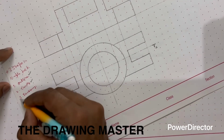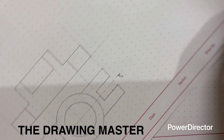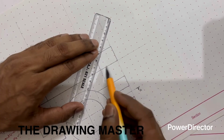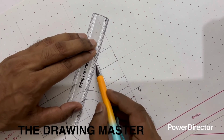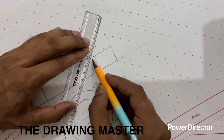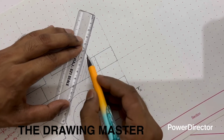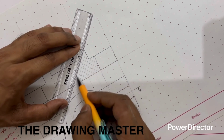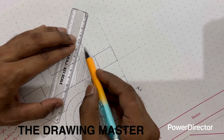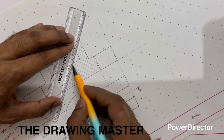So this is the third step. After identifying the cavity, you have to do the hatching in remaining area. So this line should be at 45-degree angle. You can also note down the time, that how much time it will take to do the hatching. Don't draw it casually. The hatching consists of continuous thin line. After this, we will also draw the sectional side view of the object.